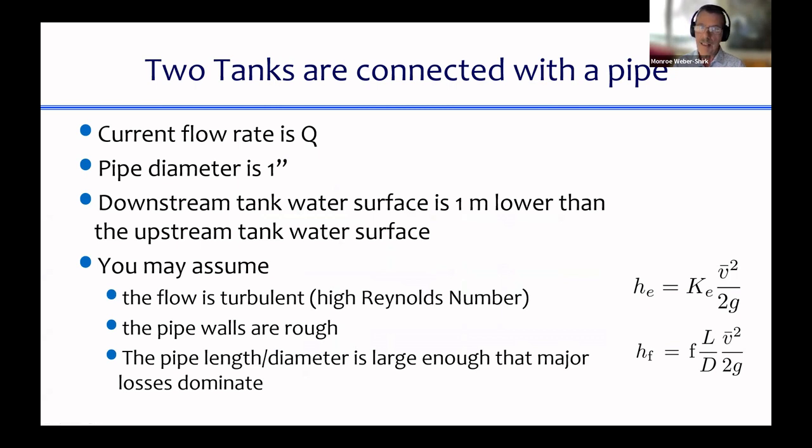And that means when we double it, because we're squaring it, instead of getting a 1, we're going to get a 4. Everybody see that? When I double V, I don't get twice as much head loss. I get 4 times as much head loss. So the total head loss, instead of being 1 meter, is going to be 4 meters.